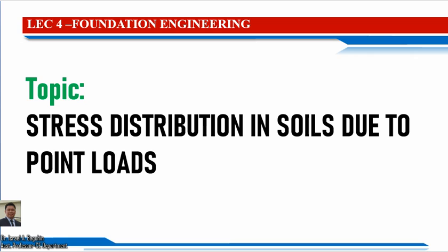According to the elastic theory, constant ratios exist between stresses and strains. For the theory to be applicable, the real requirement is not that the material necessarily be elastic, but that there must be constant ratios between stresses and the corresponding strains. Therefore, in non-elastic soil masses, the elastic theory may be assumed to hold so long as the stresses induced in the soil mass are relatively small.